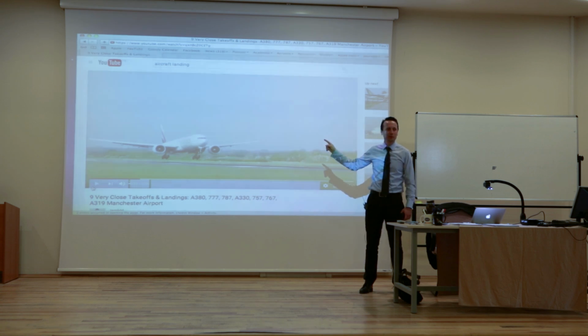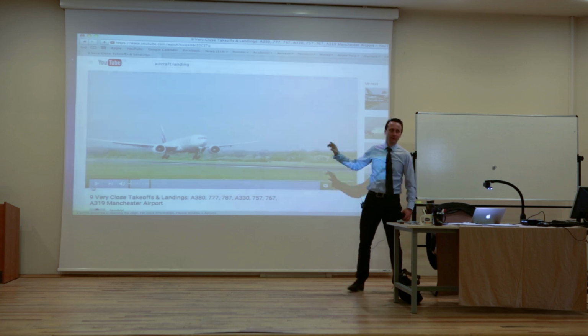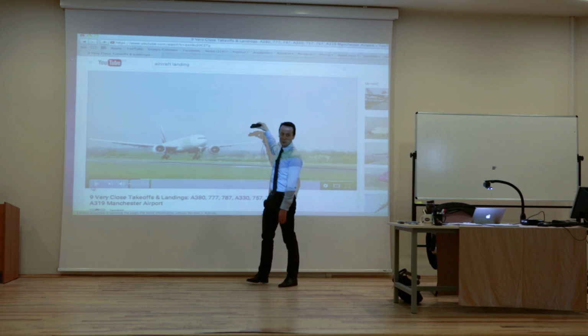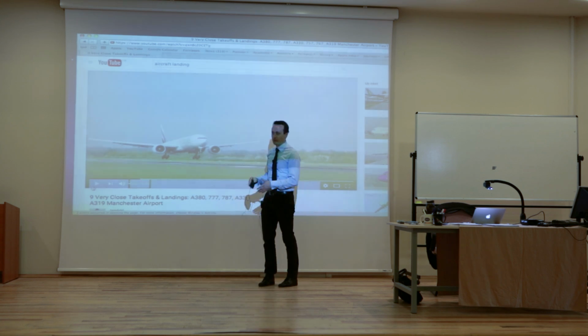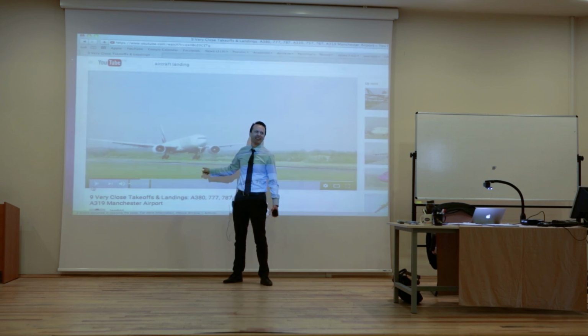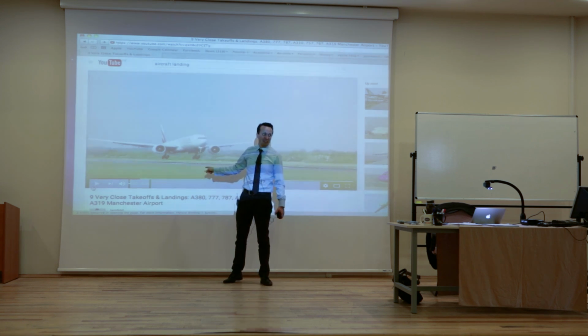Of course, from this picture, can you tell if there's angle of attack or not? No. If I just show you that picture, you cannot, because the airplane might be going like this, and it might have zero angle of attack, right? So never get fooled looking at the picture and say, oh, lots of angle of attack. Look at this. What is this angle? It's the pitch angle. It's theta, right? Doesn't mean it's angle of attack.